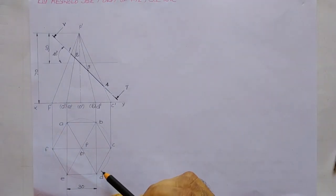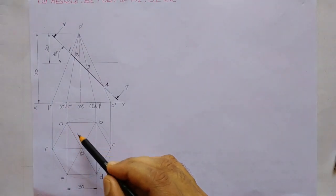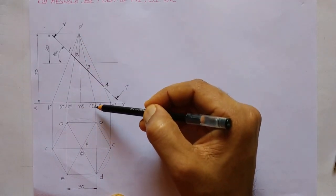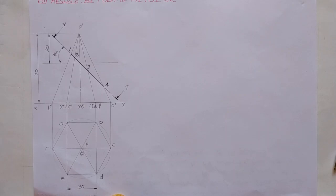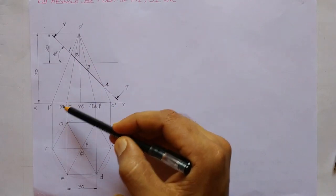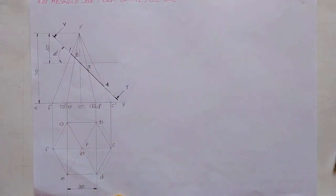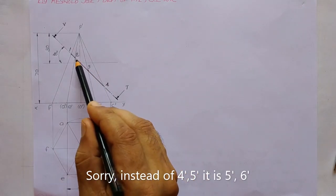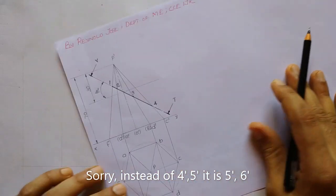On the rear side we have slanting edges PA and PB. So P dash A dash and P dash B dash are not visible in the front view. There also we will have a meeting point of the section plane with P dash A dash and P dash B dash, which are invisible. We shall mark those invisible points. Here we shall mark it as 4 dash and here we shall mark it as 5 dash.